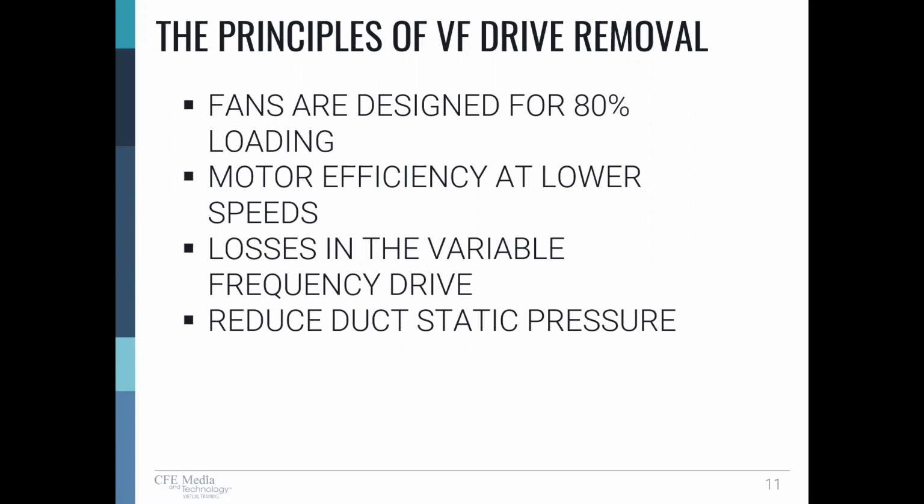When you add a VF drive, you have insertion losses, which are also a loss of power. And if you can reduce the static pressure in the ductwork so that you don't require as much horsepower, you can end up saving operating cost.